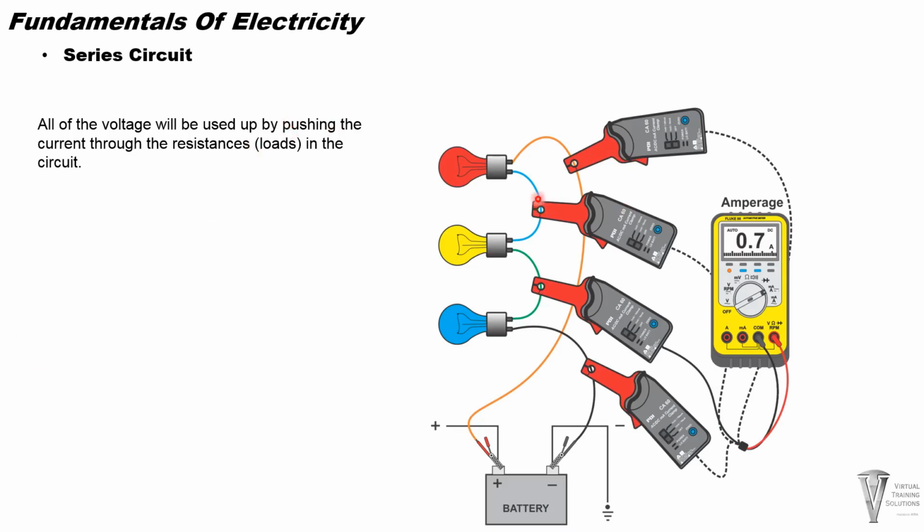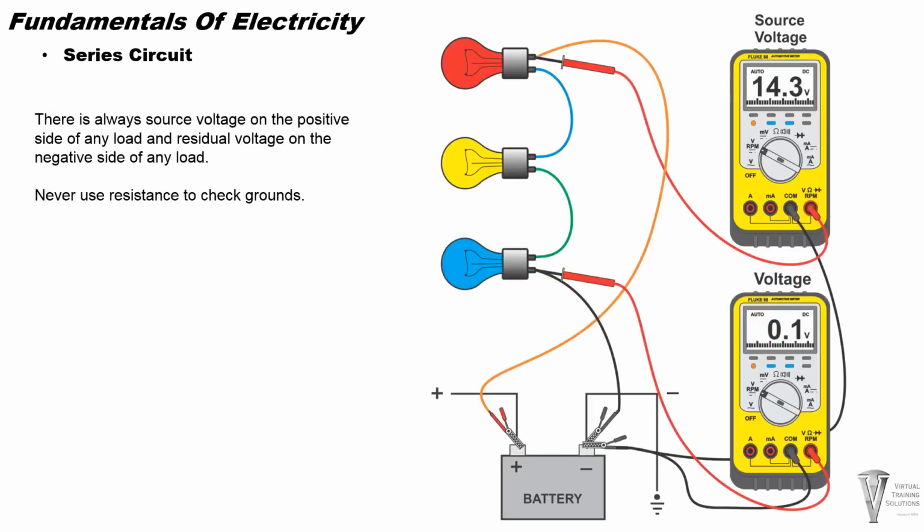Now, as a note, if there was a glitch in one of these resistors or a glitch in the wiring, that number would change. So if the resistance changed, let's just say this was open, or the resistance in the circuit here was different, if we had put a 50 ohm resistor instead of a 20 and a 20, that number would change.